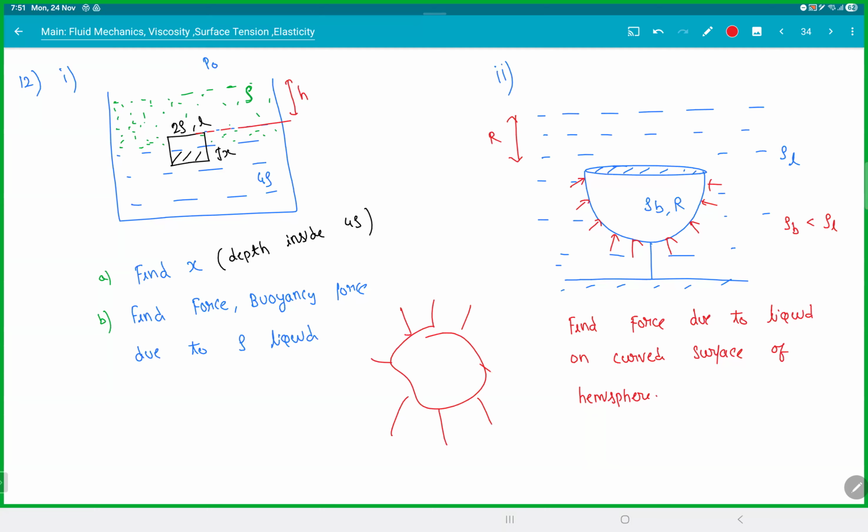But Archimedes, when he was figuring out this stuff, he didn't have a concept of pressure. You're getting it? So buoyancy force is nothing but the difference in pressure between the lower and the upper surfaces. So the moment you use the word buoyant force, you should not mention pressure anywhere. It's already taken care of. If you want to use the word pressure, don't talk about buoyant force. You can use only any one of them because both are talking about the same thing. Right?